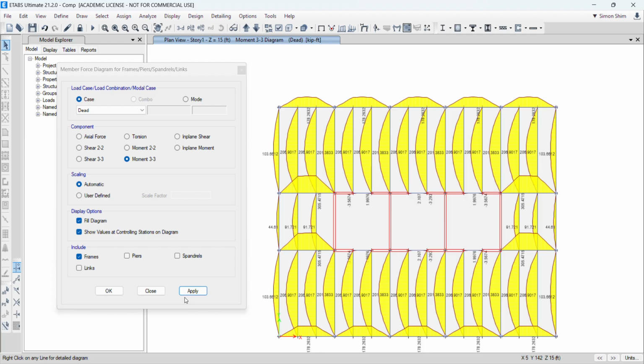First thing, I want you to pay attention from now on. As engineers, when we model, we make a lot of mistakes because we click the wrong point. Maybe it looks connected, but it's not connected. Then you will see a weird moment diagram or weird displacement, right? This is QAQC work. You need to always observe and do some QAQC, make sure everything is correctly clicked and developed. This is one kind of QAQC.